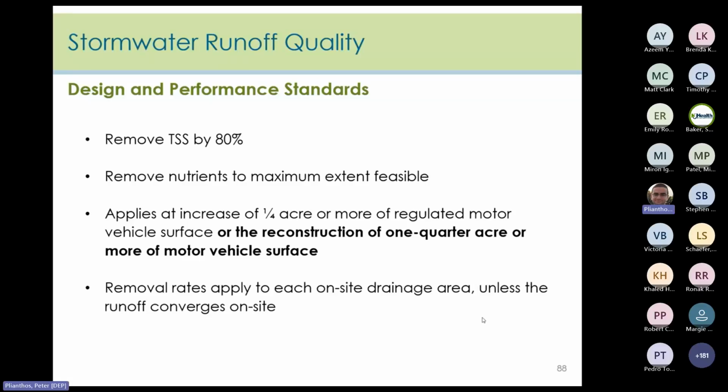Now let's also talk about total suspended solids, or TSS, for a second. It's a measure of the concentration of solid particles that are suspended in water as opposed to dissolved. This includes things like fine particles from tire wear, heavy metals, and hydrocarbons from brakes and emission, dust and dirt, particulate organic matter such as leaves, and just general trash from the site.